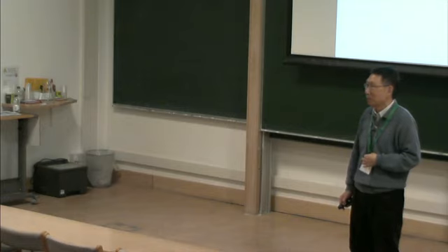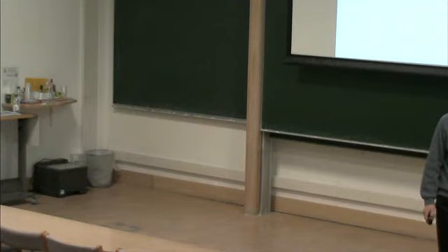Any other questions? You have a formula for the broken front propagation, and you showed it's less than the shallow water wave celerity. I wonder if Danny Dumont's data can be used to check that. I think it's different waves we are talking about. This is a long wave, a shallow water wave, not periodic. But to the extreme, we take the limit. It's the same thing.